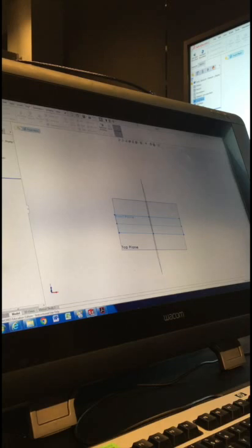So to do that, what you can do is select a plane. You can see here the difference. I've selected the front plane. And if you have that little shortcut menu come up, you can see this icon here, normal to, which is a plane with an arrow going up. If you click that, it'll take you to a view directly above that plane.